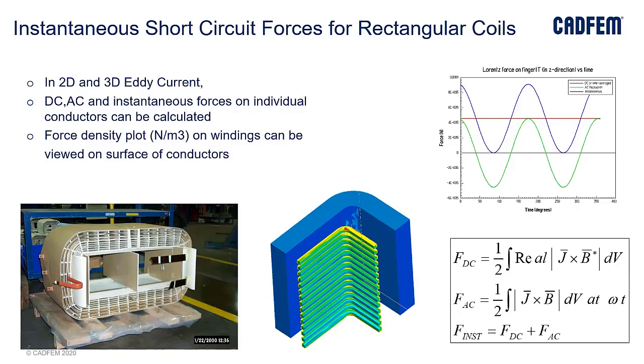Okay, so that is the beauty of FEA analysis. Here you no need to do the complete setup of the transformer. You can see here this is the physical prototype and how we are modeling the transformer in the FEA analysis. Here, if you can see this, we have modeled only the 1/4 of the model out of the complete model. Actually, I think it's not even 1/4, it's 1/8 model, because we have modeled only this part. Here we are able to see the instantaneous forces which are acting due to the DC as well as the AC components, and we can compute the Lorentz forces which are acting on that. Hand over to Thanos.